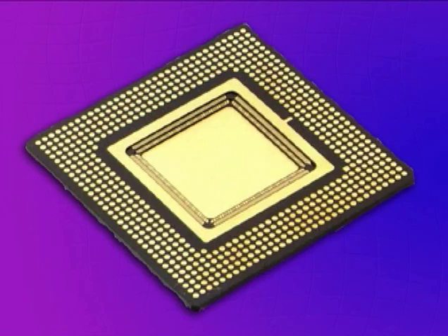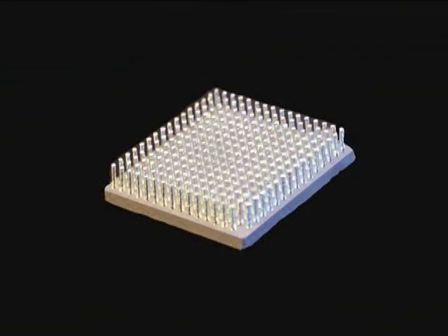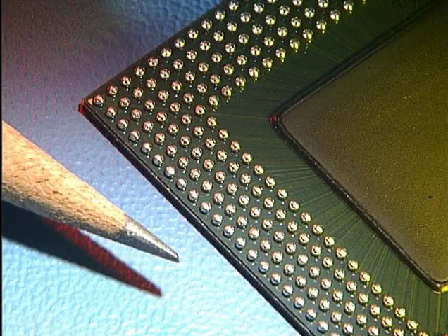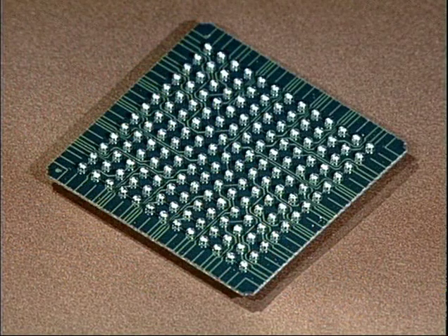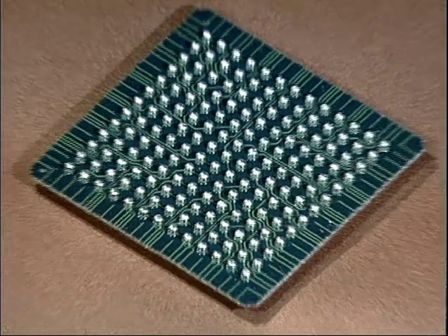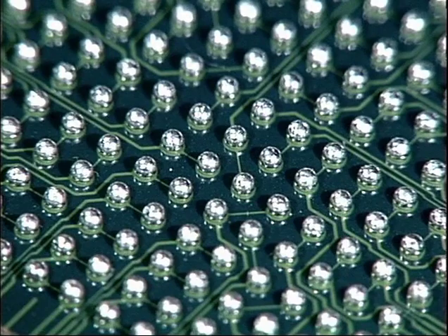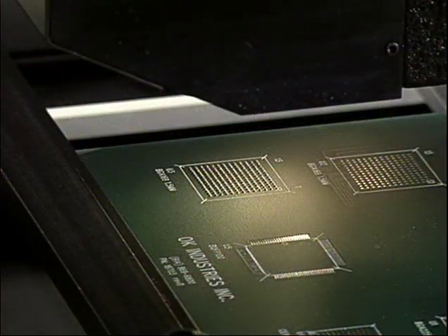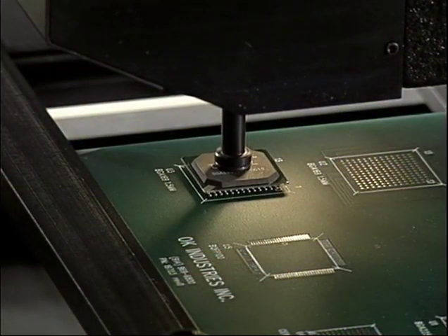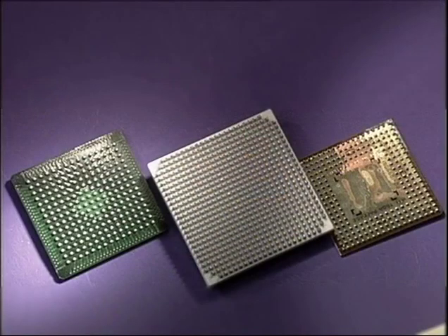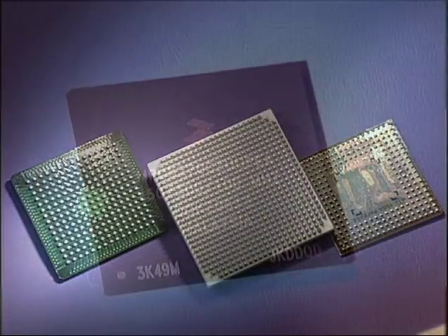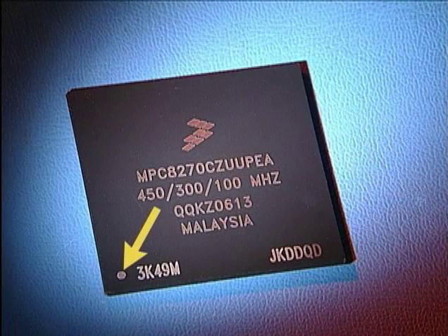The other large-scale leadless ICs are the array-style components. We'll start with the BGA. Instead of leads, the BGA contains from 25 to 625 or more tiny solder balls on the bottom of the component. These solder balls connect to a matching set of lands on the circuit board. The body of the BGA may be made of plastic, ceramic, or metal. BGAs utilize the same orientation markings as the other large-scale ICs.